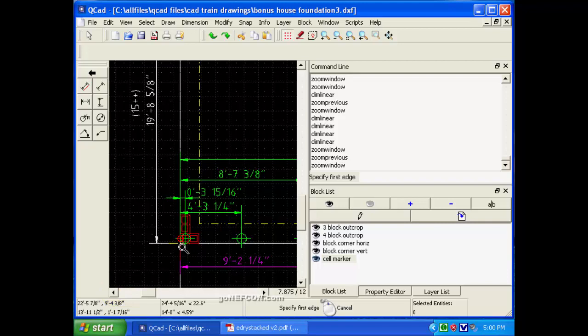So there is some slop. You can go a couple of inches out of alignment. But you want a drawing which includes all these dimensions so the person that has to drop the rebar knows where to drop the rebar on the forms. So to print out this particular drawing, you want to get rid of things you don't need.